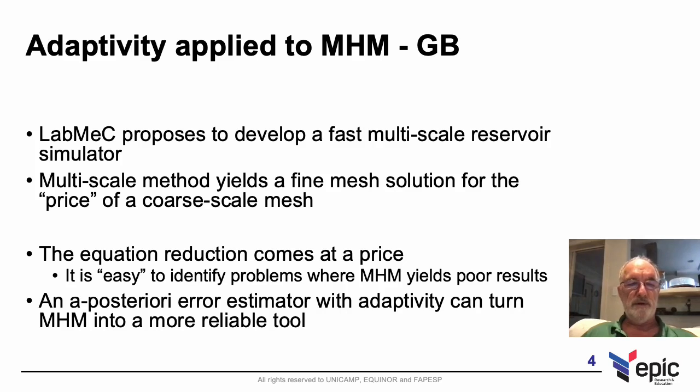The equation reduction, as I already said, that MHM results, it comes at a price. It's easy to identify problems where MHM yields poor results. But if we use an a posteriori error estimator together with adaptivity, we can turn MHM into a more reliable tool.